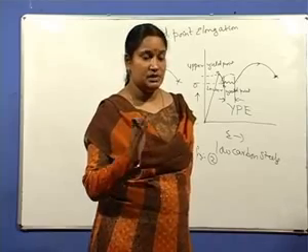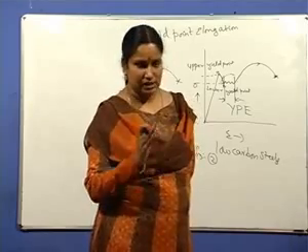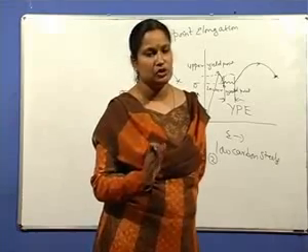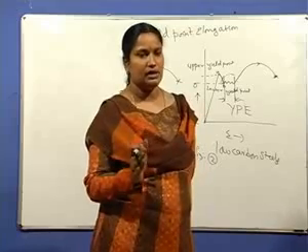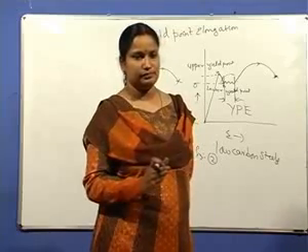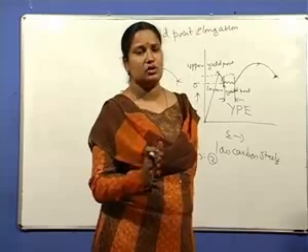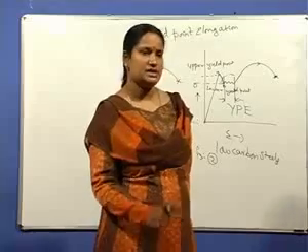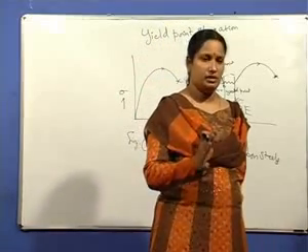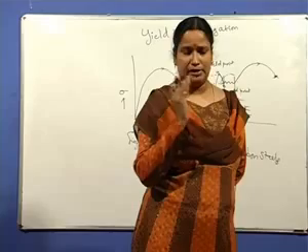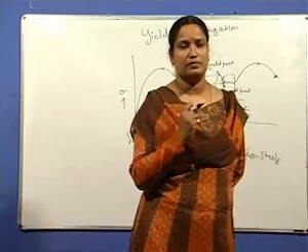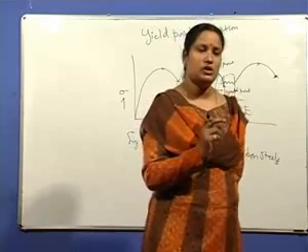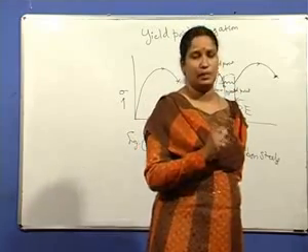These strains act as a barrier to dislocation motion, and the strengthening is due to these strains. That strengthening is called solid solution strengthening. We will discuss solid solution strengthening very elaborately in the coming modules when I deal with the strengthening mechanisms. So solid solution strengthening is one of the strengthening mechanisms.